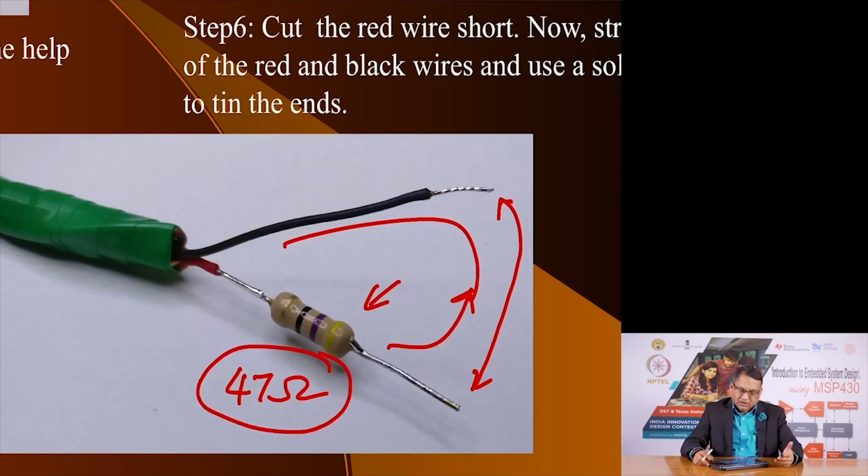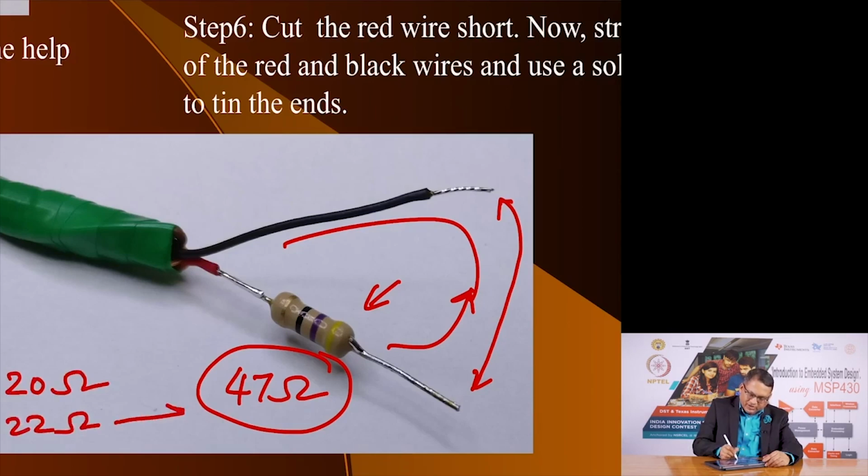If you have a lesser value resistor up to 20 ohm, that is suitable. So, you can choose a standard 22 ohm up to 47 ohm resistor like this, and once you solder it on the 2 wires, it provides you 5 volts that you can use safely to power your LCD.